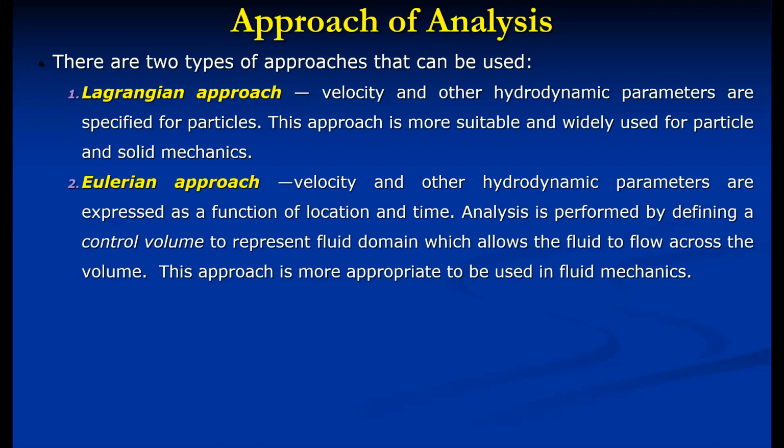In other words, the Lagrangian approach is also called a particle approach, where a particular particle is monitored and its behavior is observed. Generally, the scientists use this particular approach, and it is mainly applicable for the situation where the gas density is very low, especially in space situations where there is no contact between two fluid particles. So individual fluid particles need to be studied.